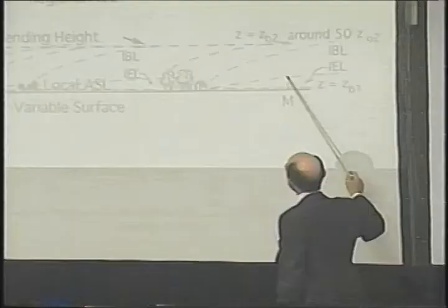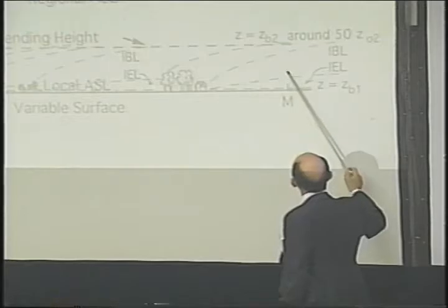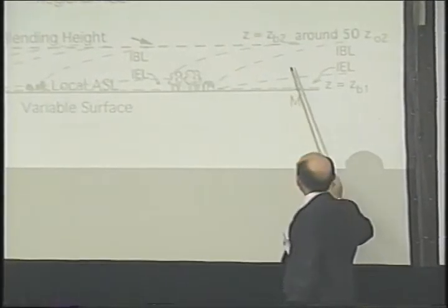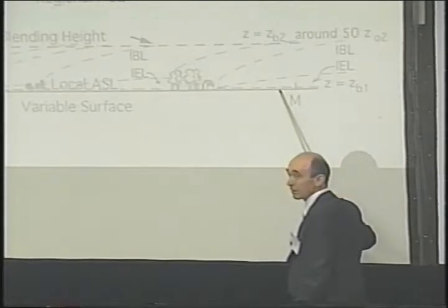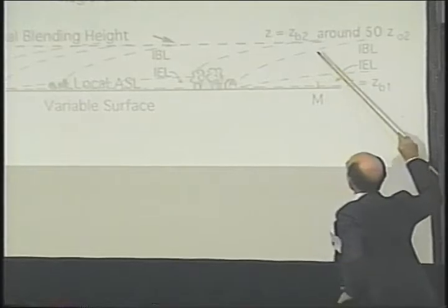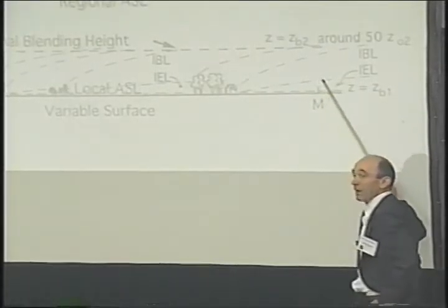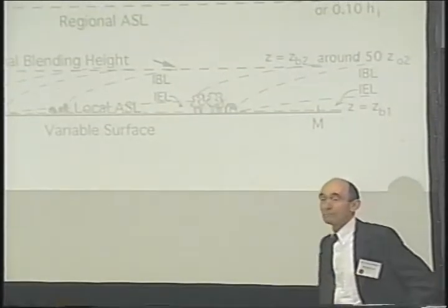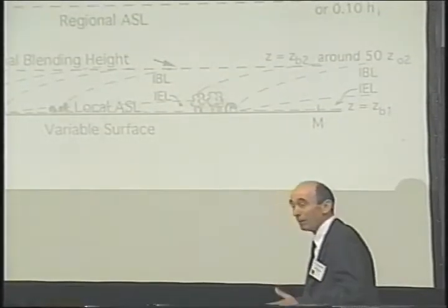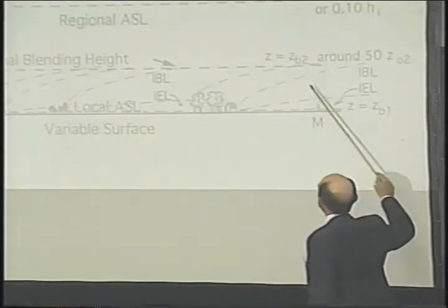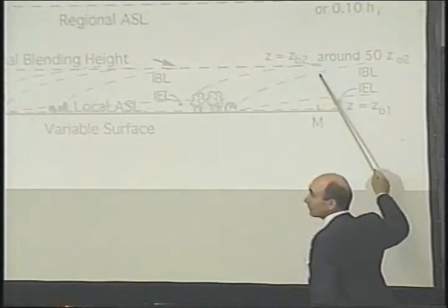As we move higher along our mast, we'll again be measuring stuff. We'll again be out of luck. This is a highly disturbed region. It's the outer region of the internal boundary layer, again, for which we don't have any good theory. Some studies have been made on this, but they all have been ad hoc for special situations, and there is no general similarity available. So we're out of luck.